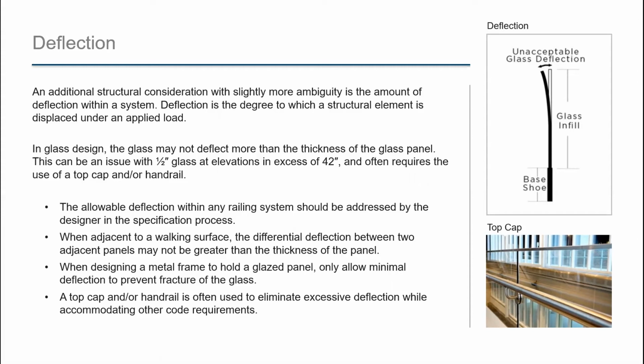To go back and discuss differential deflection a little bit, that's the deflection of one loaded panel of glass relative to an adjacent unloaded panel. As we discuss it here, that limitation is used to prevent creating a pinch point between panels where your hand could get caught. Note that this is a general building code requirement for interior glazed areas, probably more intended for storefront glass, but the implication in code is that this would also apply to guards. There are glazed areas as well, both interior and exterior.